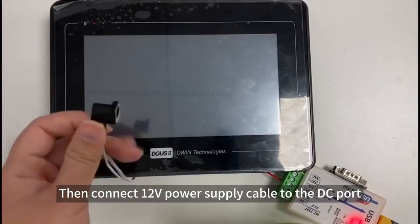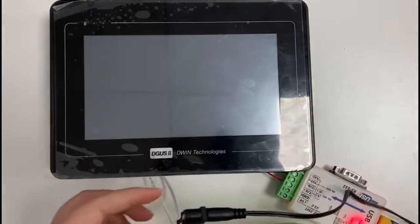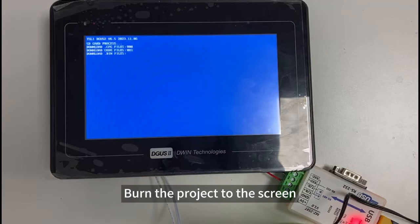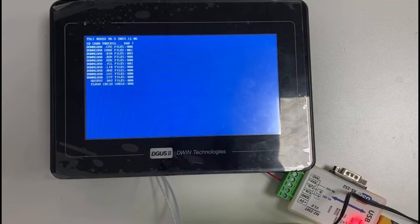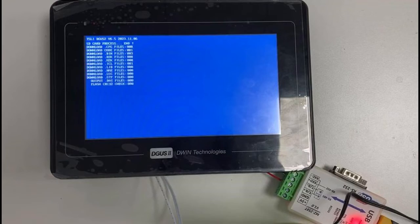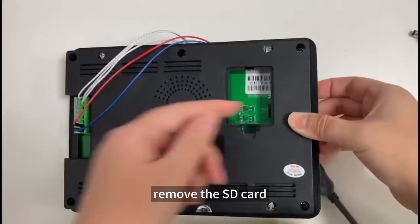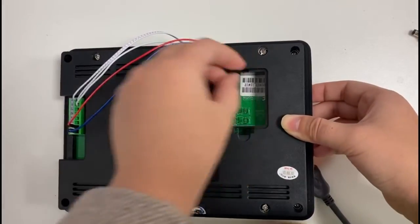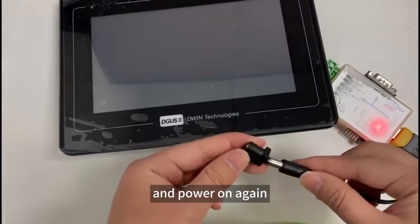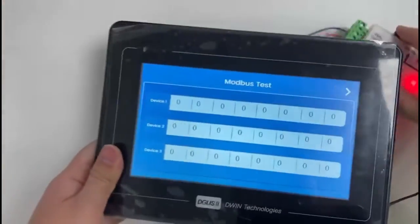Then connect 12V power supply cable to the DC port. Burn the project to the screen. Blue screen showing end indicates that burning is complete. Then power off. Remove the SD card. And power on again. We can see the initial interface.